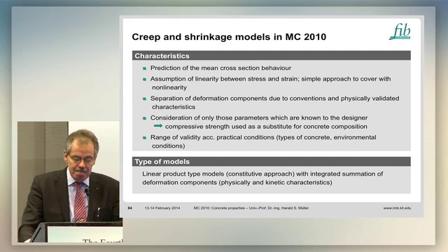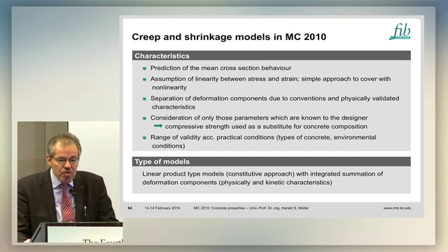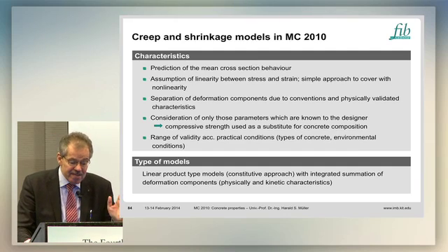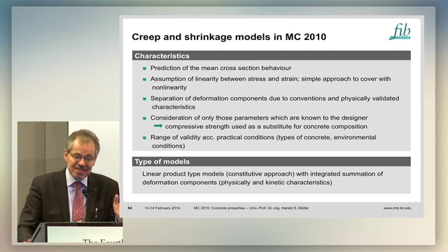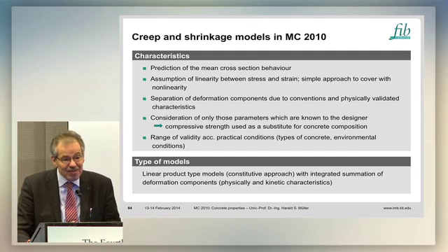And then also a very decisive point, which parameters should be included? We decided to include only those which are known to the designer. This means that the compressive strength forms the substitute for the composition of concrete.